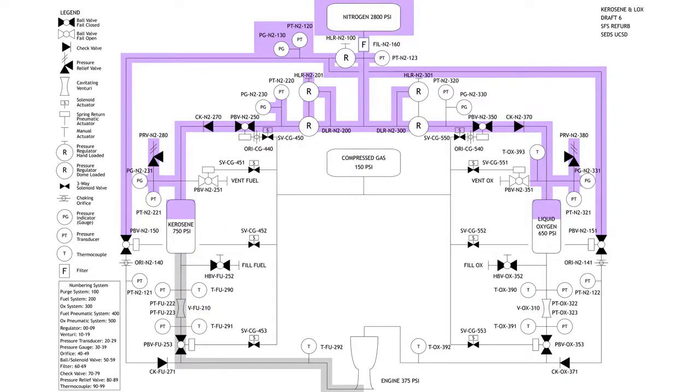propellants out. After we close that oxidizer valve, you're still going to have propellants sitting inside that line between your engine and that closed valve. So you need to make sure that those have a reason to go through your engine. So you turn on your purge to push out the remaining propellants. That's what it does, to prevent liquid oxygen from sitting inside our system and our pores. That's why you purge. Any other questions? These are all good. Cool.